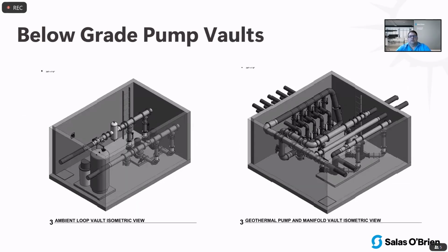The other thing you could consider is, what if we do this below grade? Okay, so now we don't have to look at anything. Everything is below ground. But what are the implications of that? Well, number one, anybody that's owning, operating, and maintaining these systems has to have confined space trained and certified service technicians to be able to access those vaults and be down inside those spaces. It does make for more challenging maintenance and repair if needed. You also have a very high humidity environment, so you have to be careful with some of the materials that are used.